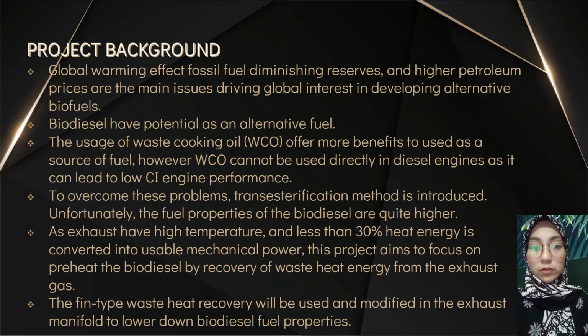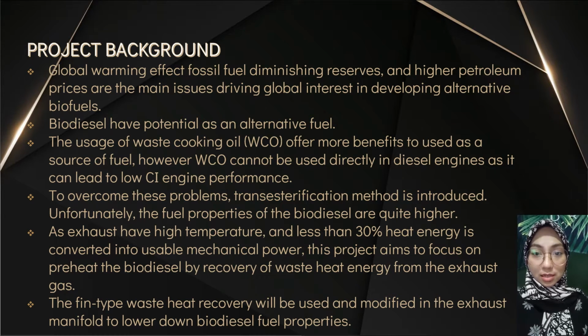Thus, a lot of research is done to minimize energy loss by using waste heat recovery systems at the exhaust gas, which is high in temperature. Therefore, to further improve the performance of the CI engine and reduce greenhouse gases, this project is aimed to focus on preheating biodiesel by recovery of waste heat energy from the diesel engine exhaust gas by using a waste heat recovery device. The fin type waste heat recovery device will be used and modified in the exhaust manifold to preheat the biodiesel fuel.